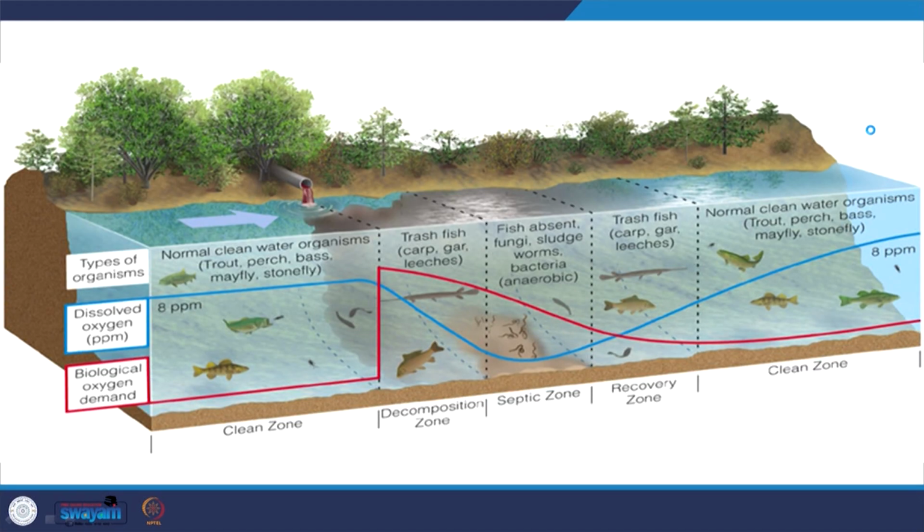So, here we have an example; we will just take a holistic view and move on. Here I have my stream coming in, and upstream of that my dissolved oxygen is pretty good and the BOD, or the organic content, is very low. So, the aquatic ecosystem is thriving, let us say. But right at the point of mixing, BOD is very high in my particular wastewater, so the organic content in the mixture of the river and the wastewater takes a huge jump. DO does not fall immediately; it will decrease but will not fall immediately.